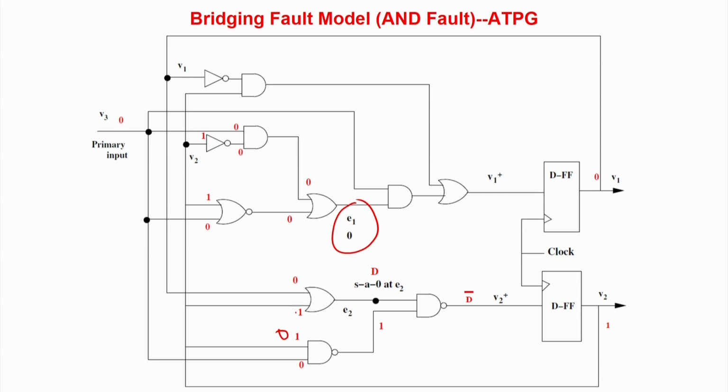And as I told you, you can also have a 1, it's possible because 1,0, 0,1, 1,1 all can give a 1 at the output of the OR gate, that is at E2. But now if you take a 1 over here and a 0 over here, as this is the same line, there will be a conflict. So there will be an issue. So you can see there are a lot of conflicts over here, and then you have to again reiterate. So this is standard reiteration.